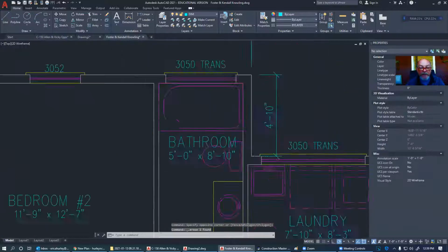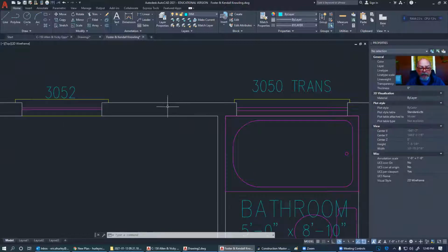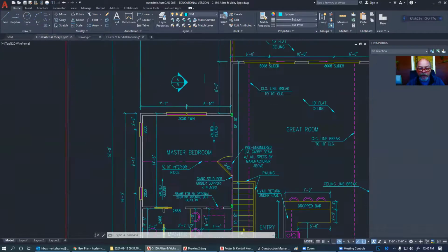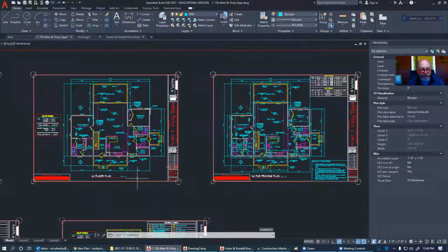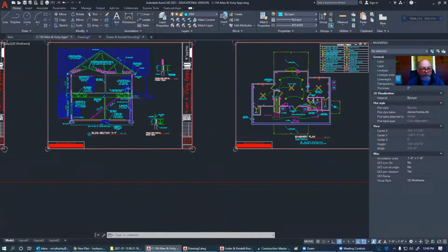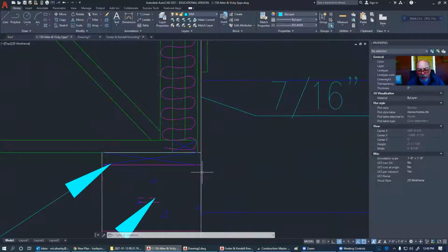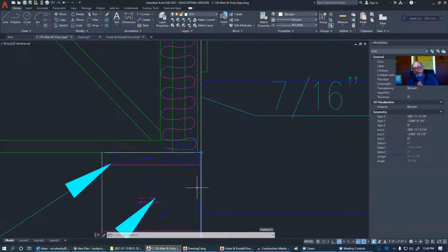All right, you're going to have to figure out on your house where the sheathing falls. Does it have brick? And where it is equal to the foundation. So go around to an access door or something where you can look at where the foundation comes to it and see, because you need to be able to dimension to your foundation wall.